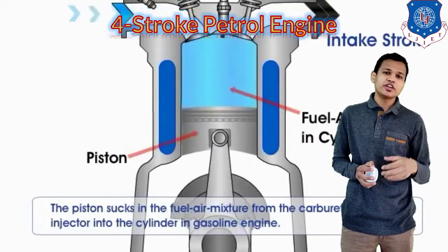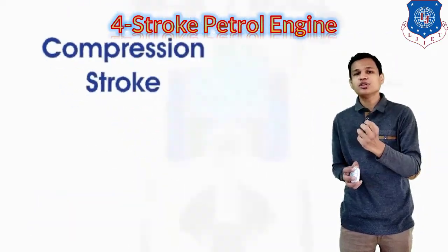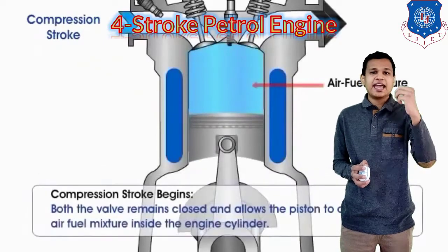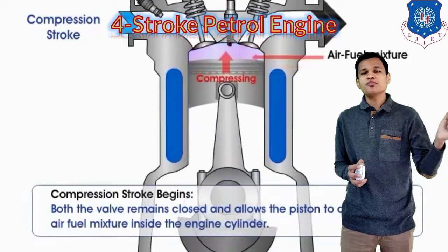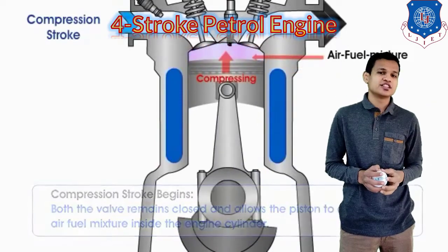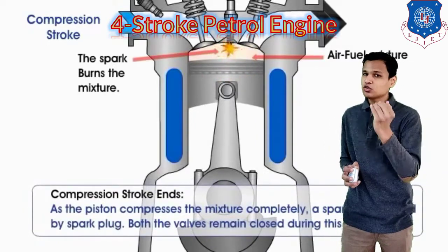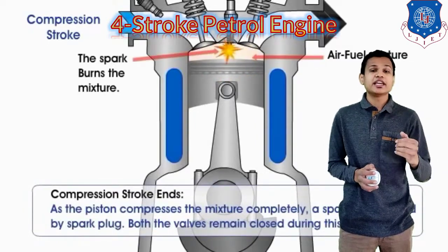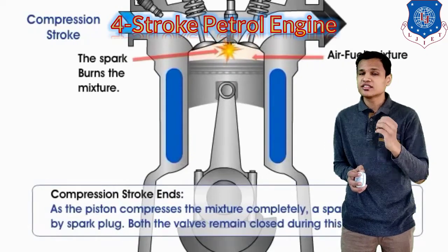But in the newer versions, we are using the fuel injector, which injects the fuel into the manifold, and in that manifold the air and fuel get mixed, and from that manifold the valve takes the charge into the engine. So we do not require the carburetor nowadays, in the case of two-stroke vehicles, four-stroke vehicles, and two-wheelers as well.